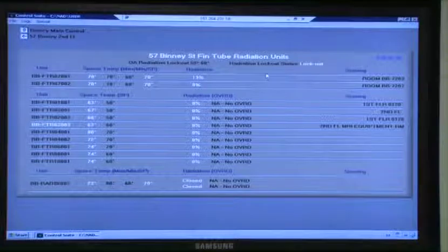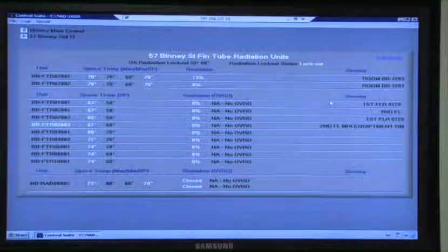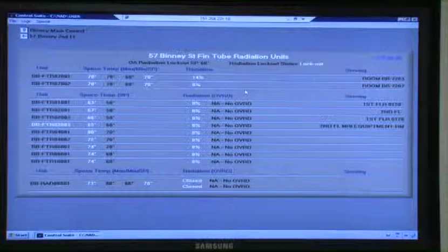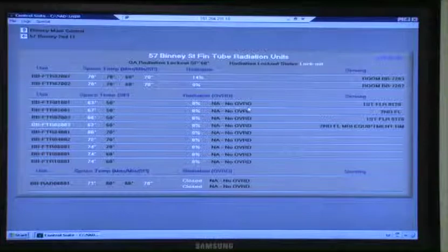So, is this block of information glycol, or we don't know that right now? I don't know if 6, 8, and 10 are on the glycol. 6, 8, and 10 are not on glycol. So why don't we do this? Take a crack at it. Break out glycol, so anything you click on glycol brings you to a glycol screen to say this is all glycol. You can label it right there. It's coming off the glycol heat. Anything that's now on base fin tube radiation that's on regular building hot water heating, you can carve that out and put it under its own thing.